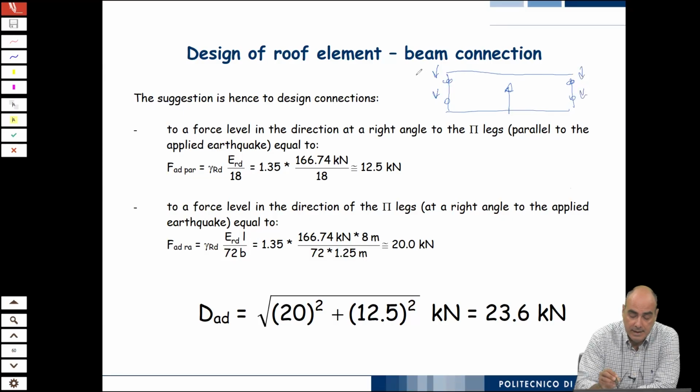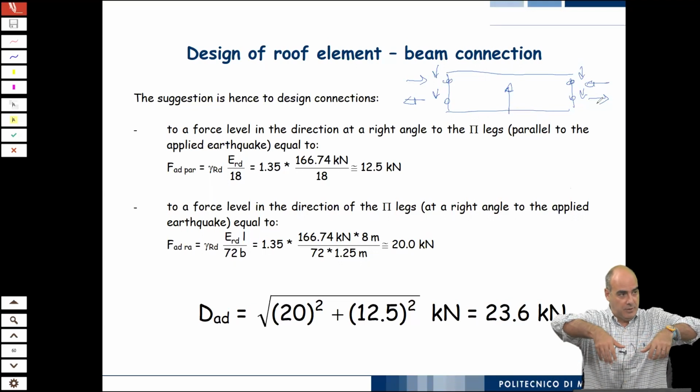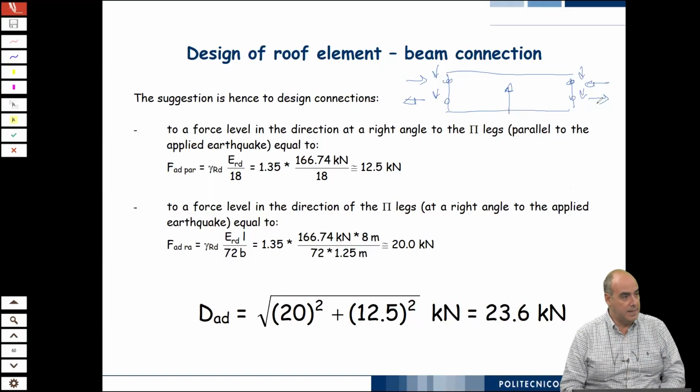So it will be like this. But you will also expect a negative bending moment, so it could be something like this. You will also expect some forces in the direction orthogonal to the force, because the diaphragm action gives you this in-plane motion that you have to counteract. You have the scheme in the same packet of slides, but it is the model that I showed yesterday.